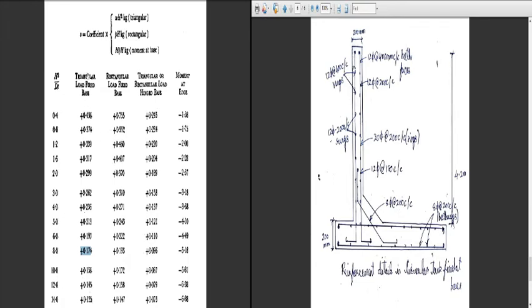Now let us see the reinforcement on the outer face. Here it is 12 mm phi at 400 mm center to center rings. Here it is 12 mm at 200 mm center to center. Here the spacing is made less, and here the spacing is made more. The reason is that the hoop tension will act here. That is why the spacing is less here, so that it provides more stability as well as strength. The bar will go in this fashion and get curtailed here, and this will go in this fashion and go inside here.